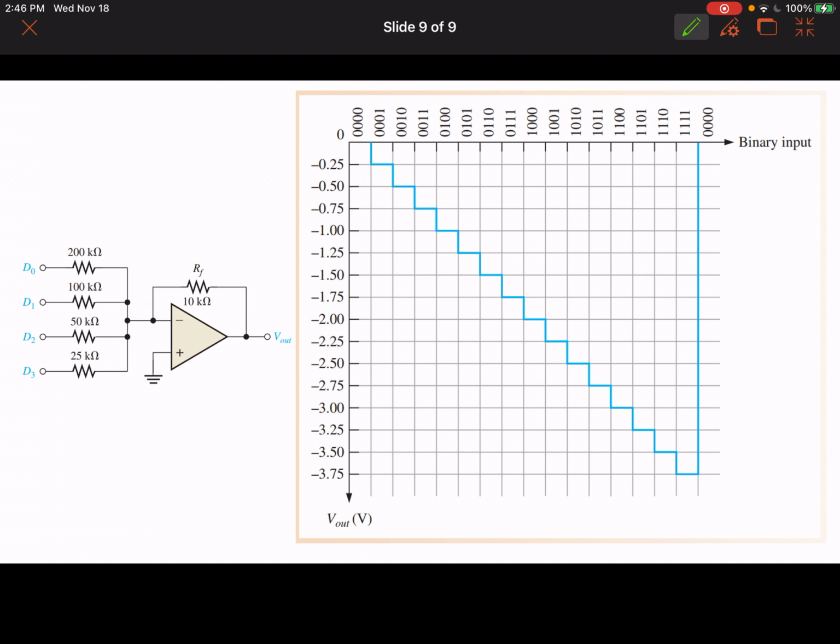So if we graph that, we will see the digital signal here, and the analog signal here. And the way it converts is that you simply add up or scale the signals using the scaling or summing amplifier. So you can actually produce a sinusoidal signal, or you can produce any type of signal. Well, here we have what looks like a triangle.